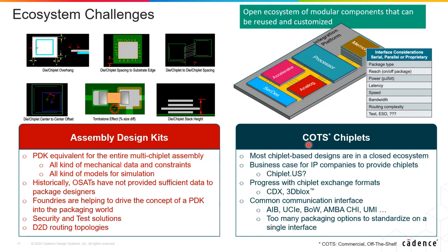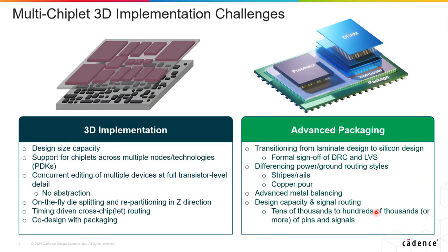There are lots of IP companies that are developing interface standards, and there are many interface standards for chiplet packaging or advanced packaging designs. And the 3D implementation. The packages are not only two-dimensional; there are 2.xD, and 3D packages are getting popular. So in the design tool, we need to support 3D interconnections as well as parallel 2D interconnections, so that new PDKs and new design tools should be developed and applied for designing these 3D packages.